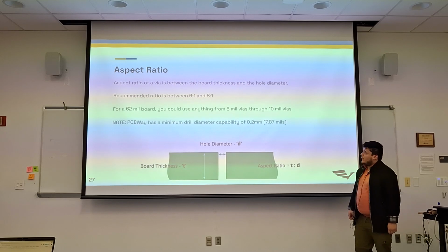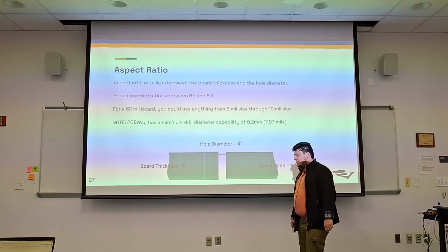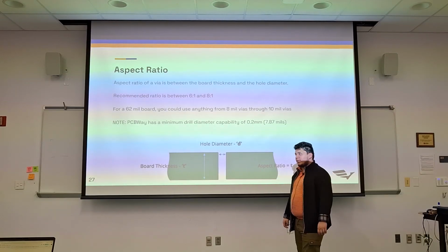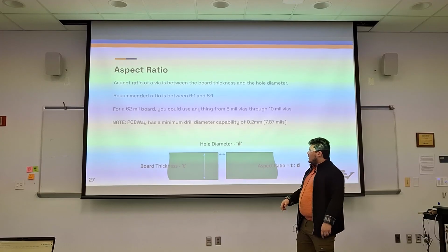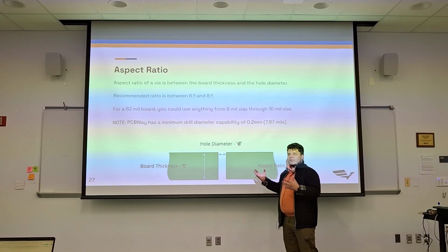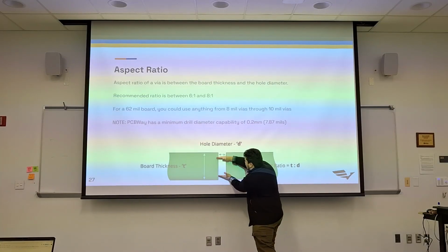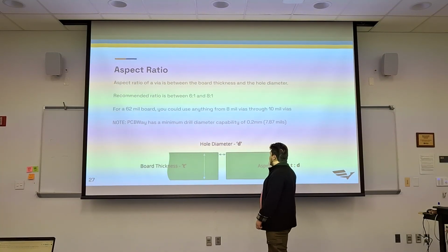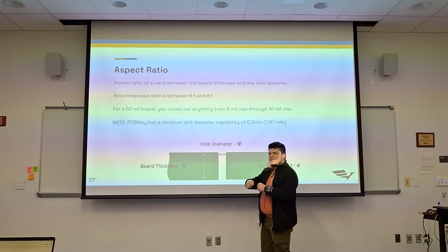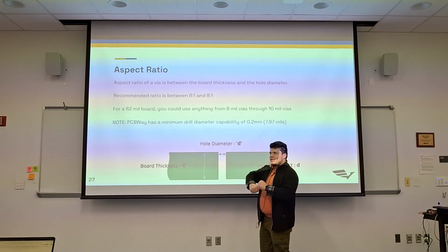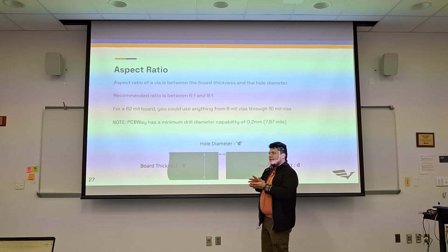But what can we control about vias? Vias are actually the first fail point in most PCB designs, because they are quite literally a hole going into the board. A hole into anything reduces the reliability. It's easier to crush this. For example, if you have your chassis ground vias around a chassis hole, your screw is going to crush them, because that is weaker. You don't have a lot of material in there.